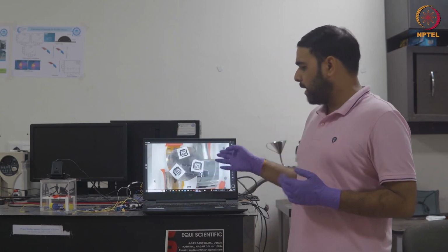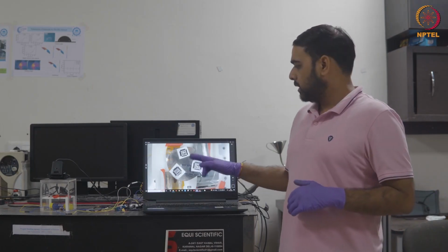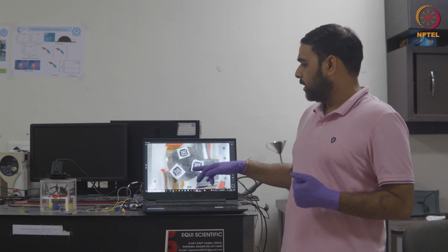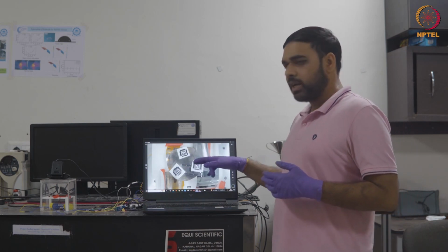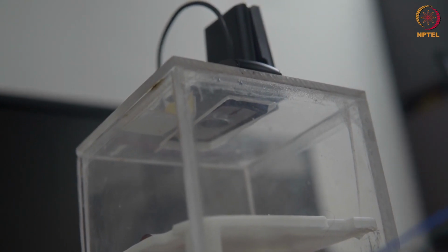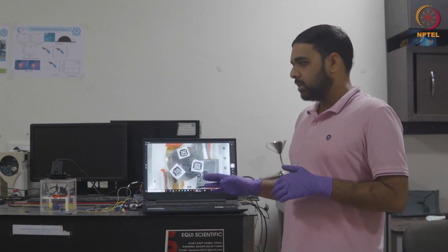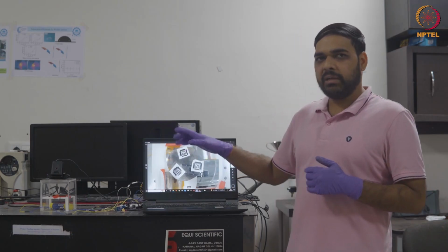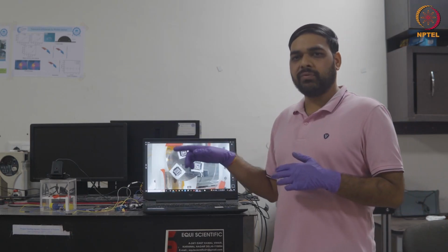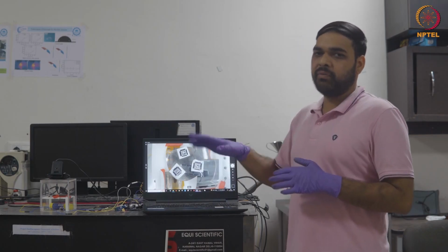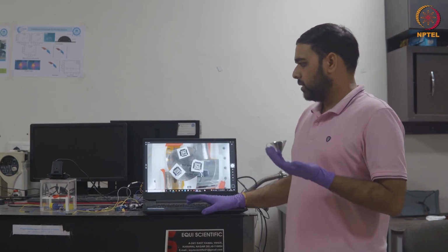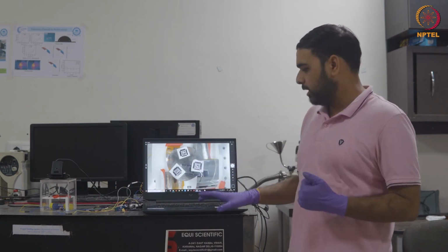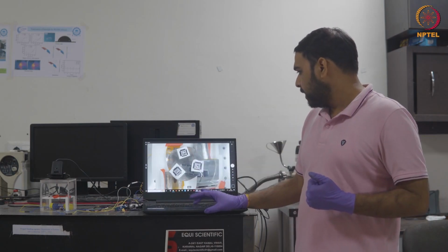And as we supply power to any one of the actuators, this mirror will tilt, and because of that tilting, the position of the ArUco markers with respect to our camera will change. As it changes, the new position will be detected by the camera, and it will again generate an equation of a new plane, and will give the final angles of the plane or the mirror with respect to the initial position.